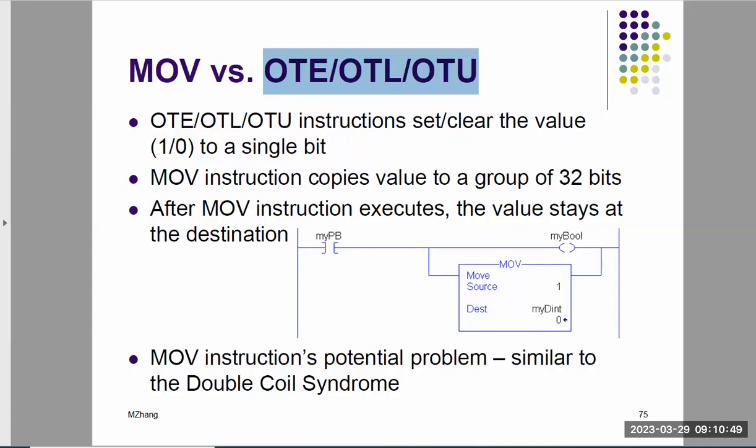So that's analog, because you don't see any limit switch. You don't see any sensors to check individual levels. We have a continuous change in the level, right? We can see the level start from maybe very low, maybe 10, 20, and go up, or go down. Either way, we see continuous change, right? So that's an analog input.